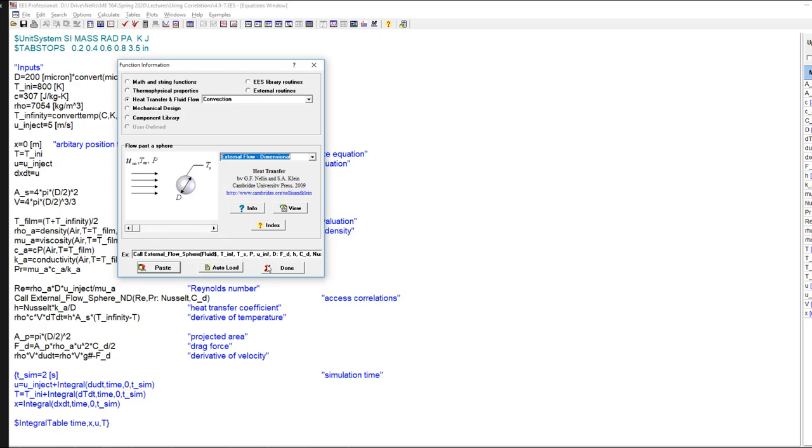So this is kind of a wrapper for the dimensionless version, right? This function will take these inputs, it will calculate the Reynolds number and the Prandtl number, it will use the non-dimensional version to calculate the Nusselt number and the drag coefficient, and from that it'll give you back the drag force and the heat transfer coefficient. So they go together. This is in some ways a lot less work than the other one, but this non-dimensional one is certainly much closer to what's actually going on, and you should understand the difference between the two.